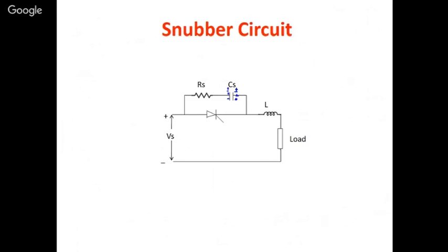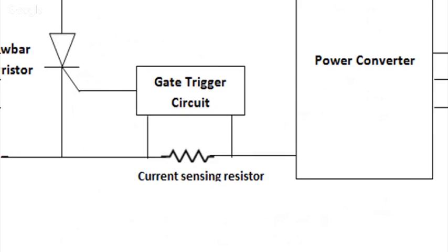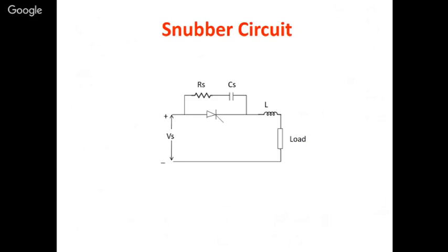After that, what happens? It goes on charging, and at one instant you will have all these plates minus and all these plates plus at the final instant. In the sense, first it was a short, 0 volts. After that, the charge started developing there, it started charging, and at the final instant it will get the same voltage here, Vs. The source voltage will come across this capacitor.